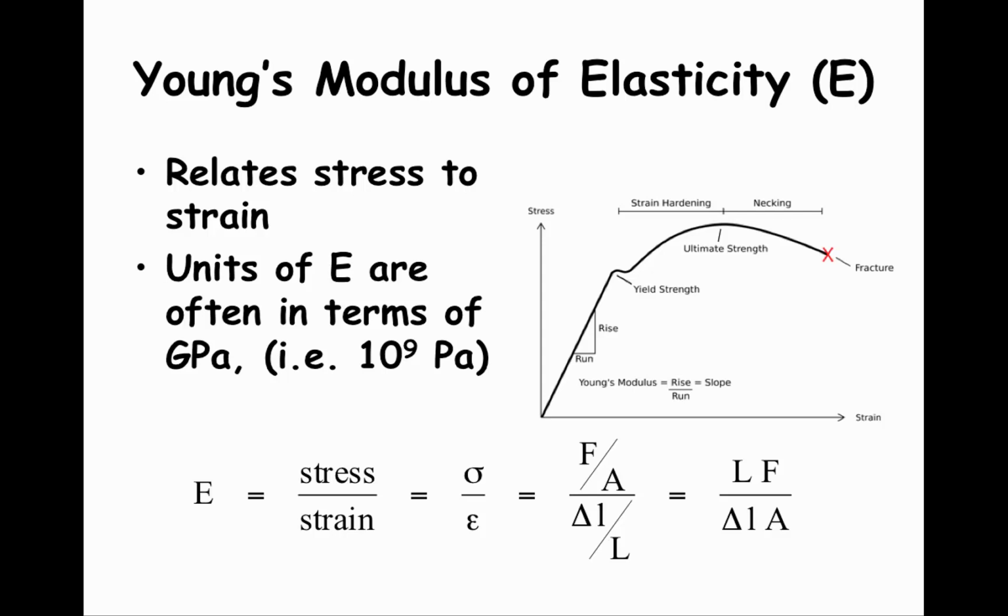If you look at the stress-strain graph, Young's modulus of elasticity applies only along the linear part of the response at low strain levels. This relation does not apply if you reach the yield strength of the material, after which the material does not return to its original shape.